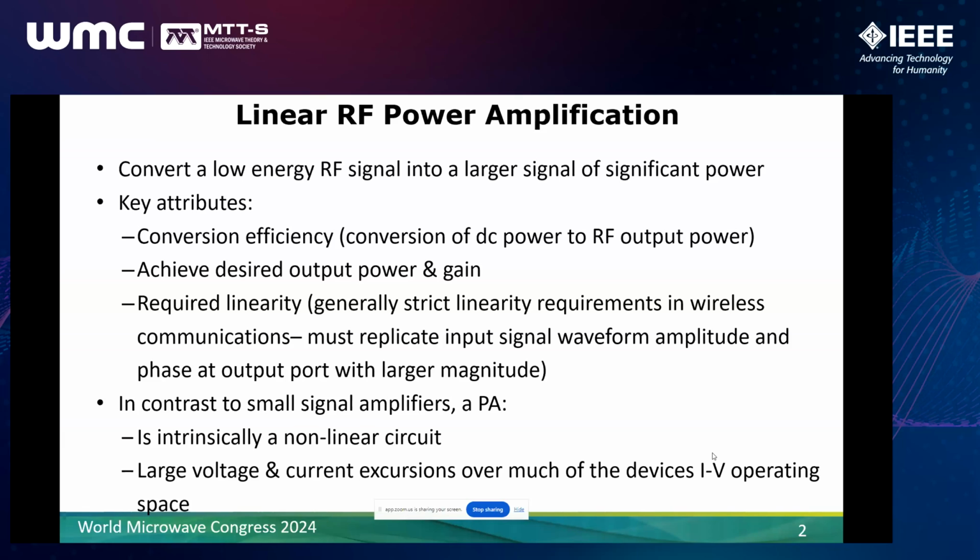First of all, a power amplifier is intrinsically a nonlinear circuit, in contrast to an LNA. And as such, there are quite large voltage and current excursions over much of the device's IV operating space. In fact, we try to maximize the voltage and current excursions over the device's operating plane to achieve the most power we can from the device and do so in the most efficient manner we can.